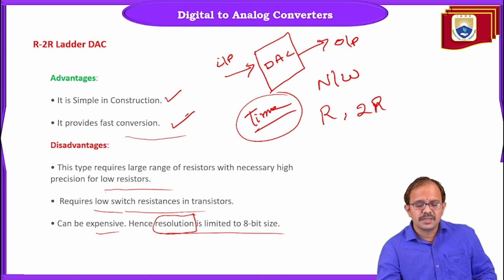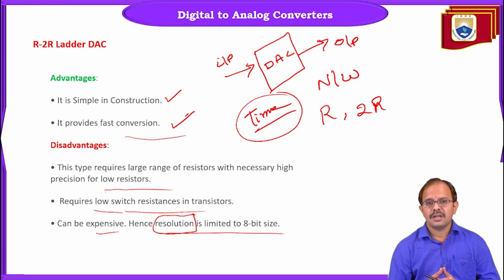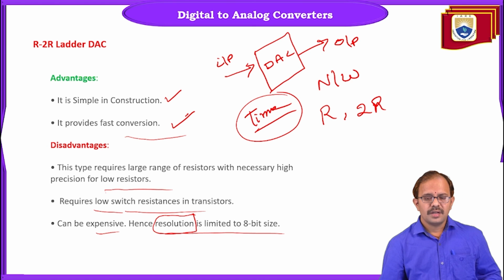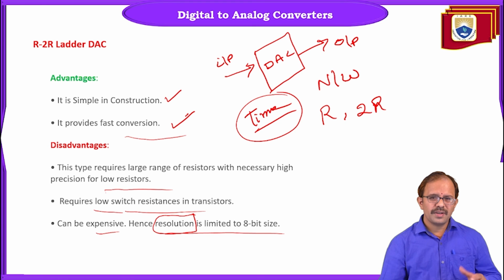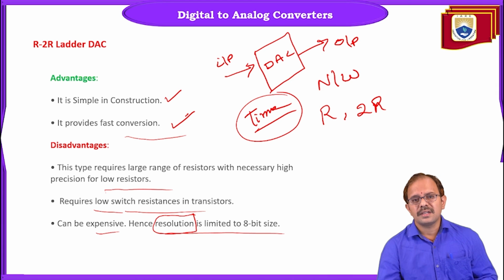In the next class we will focus on how to overcome this drawback of current, that means how to regulate or control these variations of currents. We want the currents through the resistors to be the same and uniform. If the variations in the currents increase abnormally, there will be a possibility of a high amount of power dissipation, and this power dissipation later affects the performance of the converter because of excessive heat.